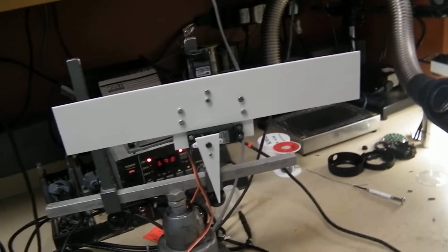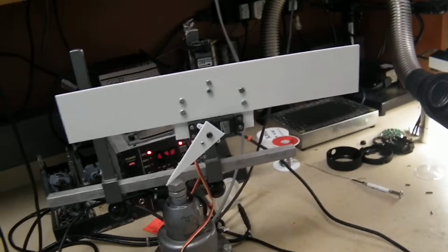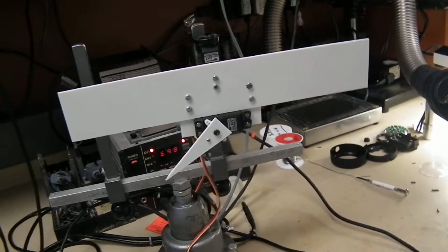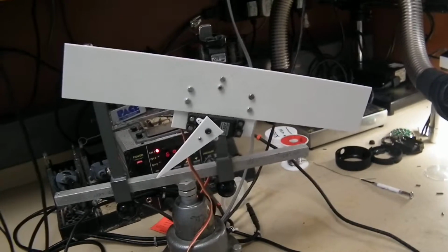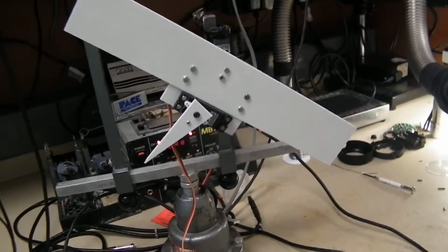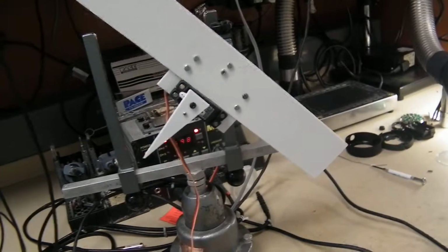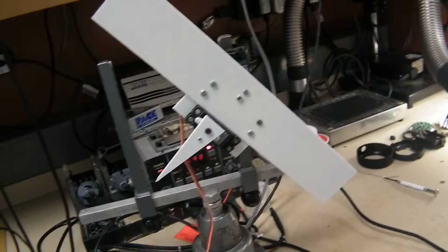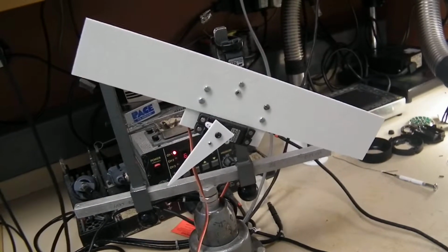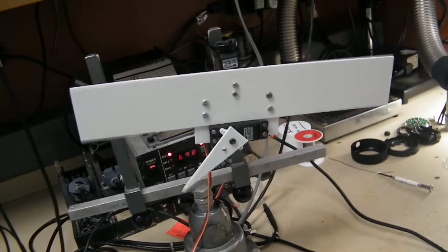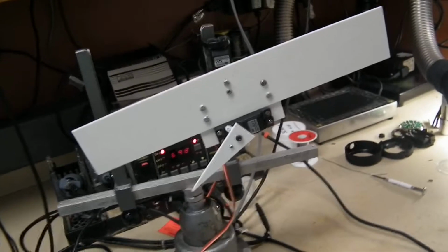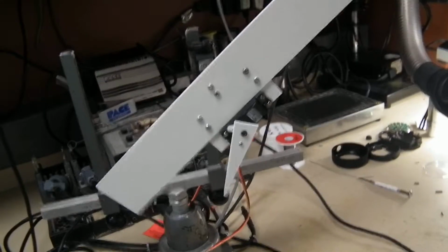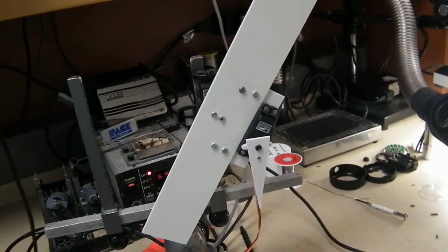Now, if we turn the camera gimbal to its extreme position, which is plus or minus 45 degrees of the center, and if we rotate the platform up, then obviously there's only so far you can go, and now the angle of the camera gimbal with respect to the platform is 90 degrees. If we then rotate the platform back to the horizontal and continue to rotate in the opposite direction, the camera can't rotate any further, so it stays at its extreme position all the way up to the other side.